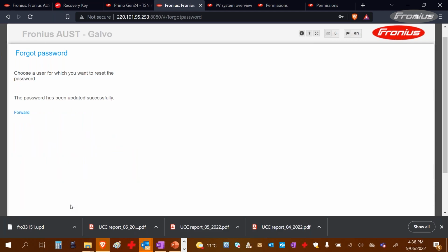Maybe if we look at an example. Let's say I'm on site on Saturday, and Fronius is not open on Saturday. Let's say I forgot my service password, because then I can't activate the first smart meter. So I go on site, I connect my phone to the inverter, I try to activate the smart meter, and it doesn't work. I go to SOS, and then I just follow those steps that you just showed me. Exactly, that's it. It makes installers more independent on site.